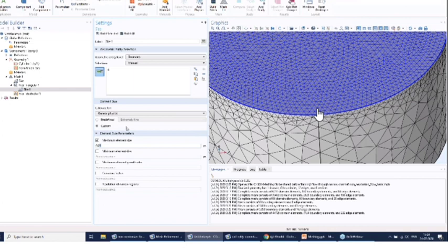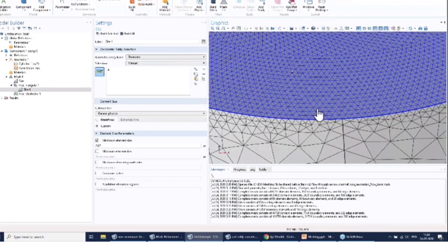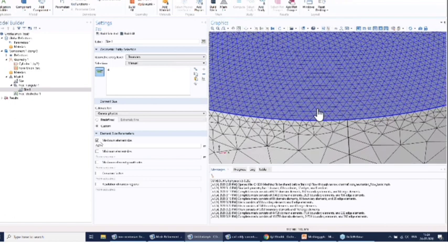Currently, using the extremely fine mesh, you are getting a size of 0.04 meter, but you can further reduce it. I will make it 0.02, and you will see that it will take much more time to discretize the surface, but you will see the effect of doing that. You can see now the size has reduced, and the maximum element size has become 0.002. Similarly, there is the minimum element size and the maximum element growth rate.